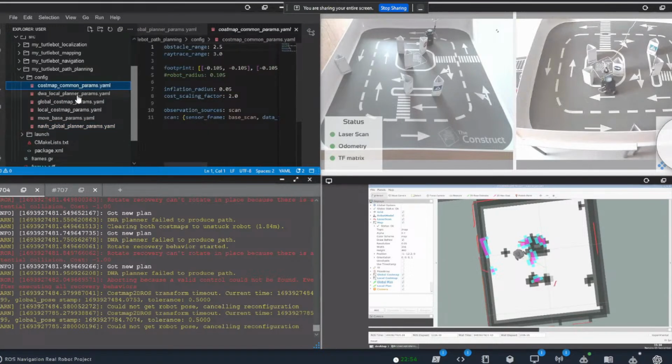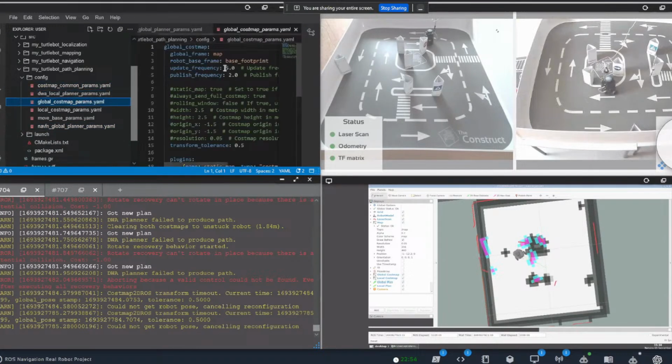But since it's a little robot, I'd say 12 hertz for both the planning and update frequencies, and see how it works out. Okay, I will try. But other than that, the biggest thing that I saw is that global path thing that I don't really understand why it was happening, and I'm sure that is the fix for these strange things you were having.